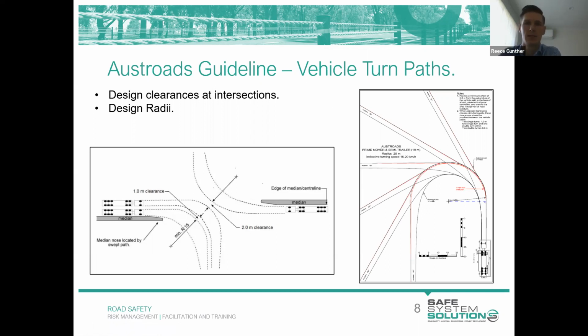In addition to this, we do adopt a 0.5-metre clearance to the outer part of the body, because when large vehicles, particularly articulated vehicles like trucks, are performing a manoeuvre, sometimes parts of the vehicle extend beyond that of the envelope, and this clearance considers that. So it's important that when you're reviewing the design that you see that line work being displayed in the diagram, and I'll touch on that in the next couple of slides.